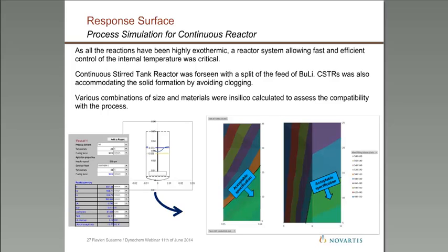We end up having a type of reactor, that means mixing time. We had different heat transfer. We had different material of the reactor, which generates the overall heat transfer, and mixing time, dimension of the reactor, volume of the reactor, geometry. As I said, all these parameters could be screened.